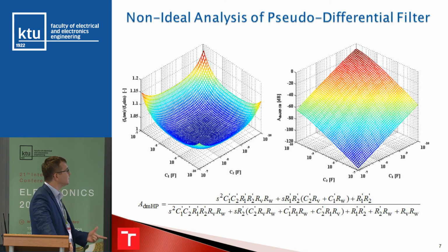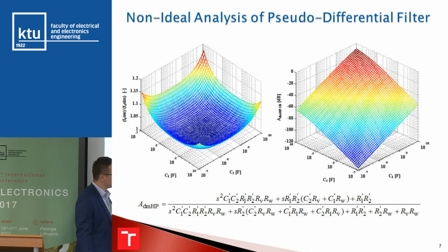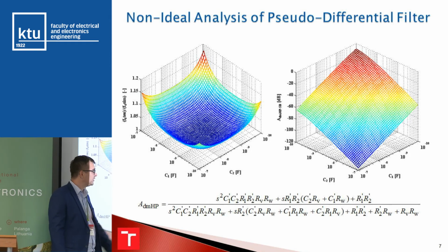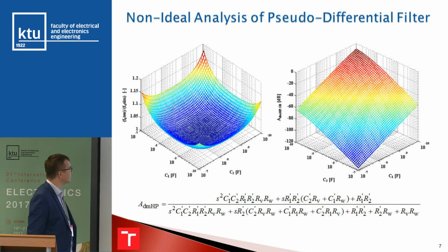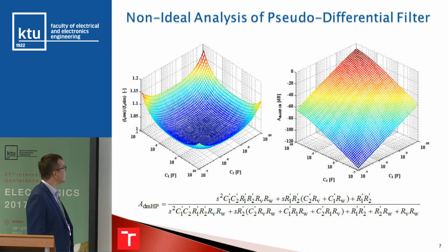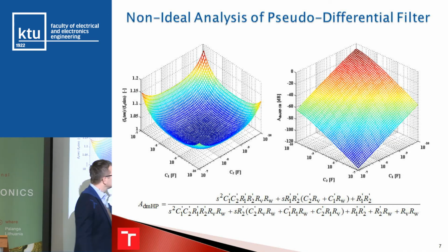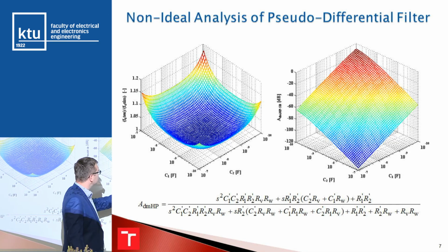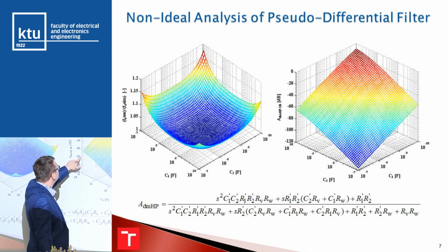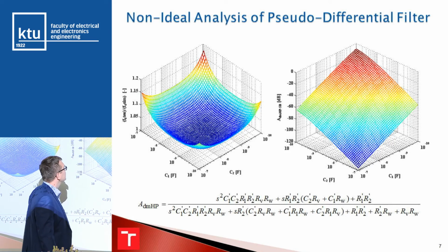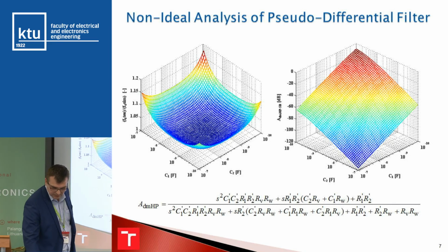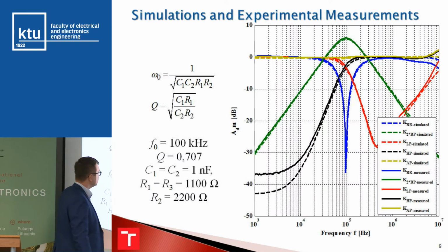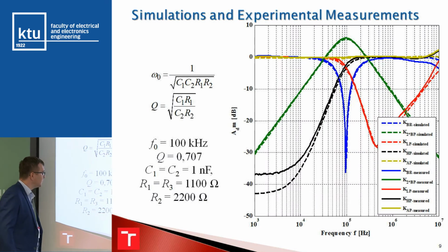This is actually the main problem, because if we also included non-unity voltage and current transfer, it would be huge, and we couldn't analyze it that simply. So here we go for 1 nano and 1 nano, and in theory we should end up with an attenuation of somewhere between 60 and 70 dB, but end up just below 40.